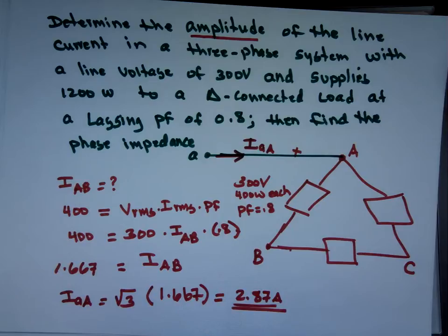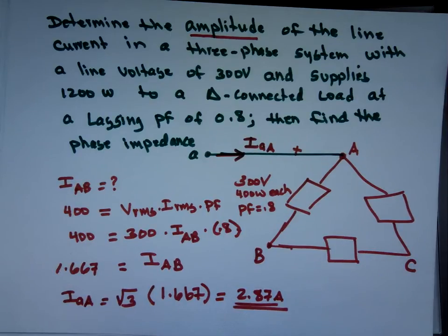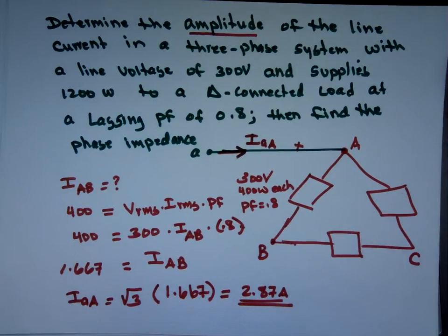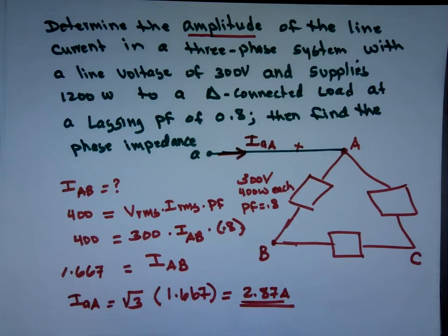Because we don't know the VRMS across. Well, it would be a phase shift, a phase difference of 120 degrees there. Yeah. So the magnitude will be the same, but the phase will be different. So that's why that number becomes the square root of 3. Got it. So instead of finding the angles of all of them, we can just do square root of 3. Yep. And the reason, let me finish this and I'll come back to that one. I'll just show you the math there.